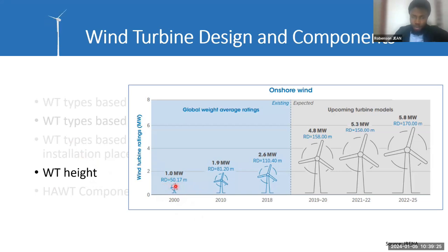But on small altitude we do not have a high wind velocity. When we get higher in altitude, we can have a higher wind speed. As we can have higher wind speed, the tallest wind turbine can have a wider swept area, like a larger rotor diameter.